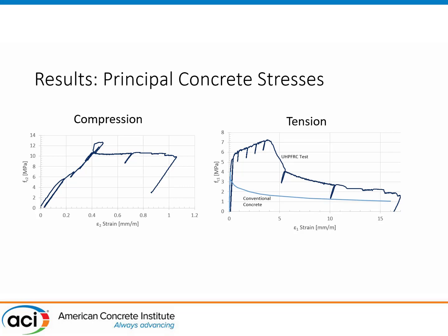The initial stiffness was what we expected to be from linear elastic behavior. After the cracks formed, there was a significant decrease in the compression stiffness, such that by the peak load, it had a secant stiffness of only about 2/3 of the uncracked response. That indicates that even though the compression stresses were going between the cracks, they were still feeling the effects of the cracks. But unlike regular concrete, where the curve will basically curve over, it went back to being stiff again and proceeded to go back up linearly again up to the peak.